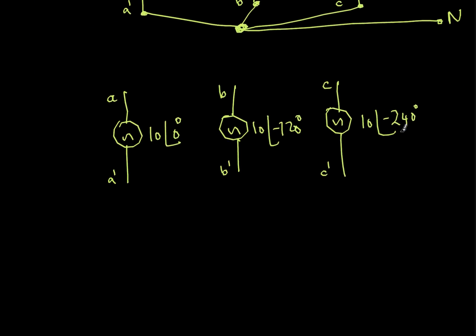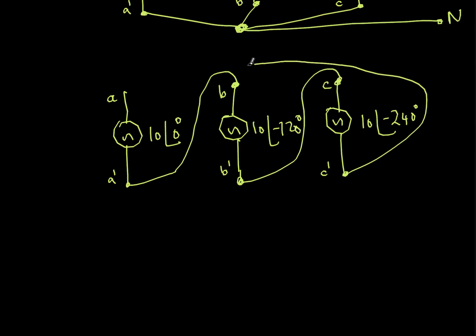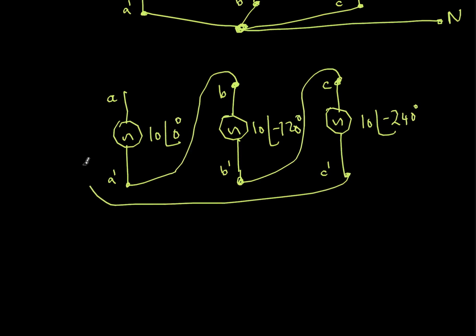Now come to another way of connecting. So what you do is, the ending of the first winding you connect to the beginning of the next winding. The ending of this winding, again you connect to the beginning of this winding. Similarly, the ending of this winding, you connect to the beginning of the other winding. And then you take out either this side or this side, so let me connect it from this side. So basically it becomes a closed set of connections.